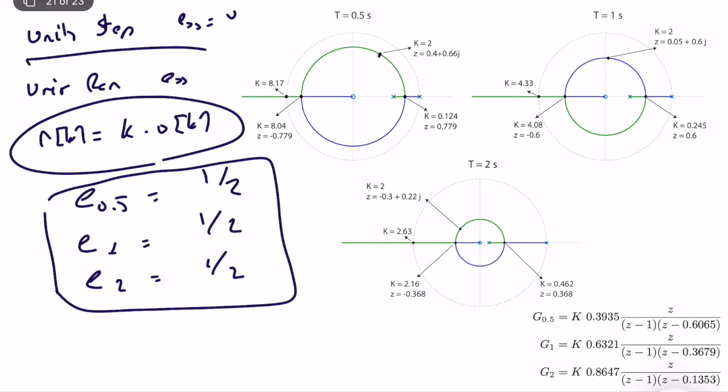So you can assume that if you keep the same controller and change the sampling time, you lose some transient performance in terms of overshoot and peak time, but settling time as well as the steady state performance is the same. But it's wrong. We made the same mistake: we evaluated the steady state error with respect to R of k. Why it's bad, I will show you.